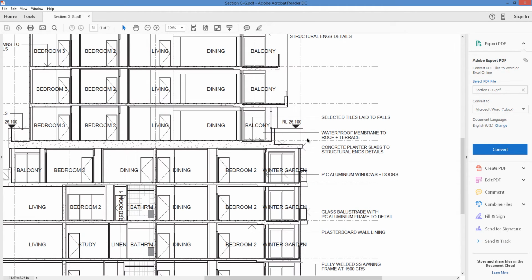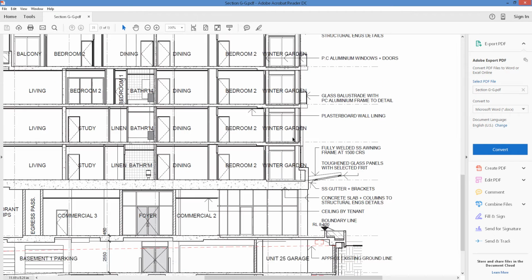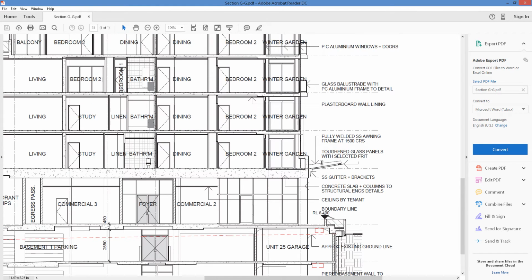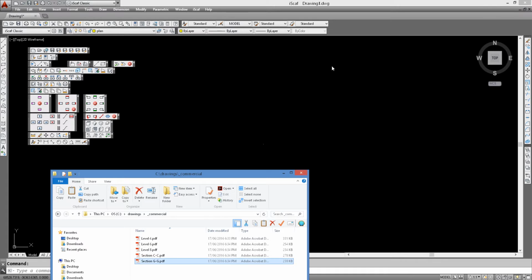So based on this information, we could probably sit some scaffold right here on this level and start it around this level further down here. So to plan this, we would like the scaffold around the full perimeter to full height, but we need it to step in at the upper level, continuing up but still joined to the lower scaffold.